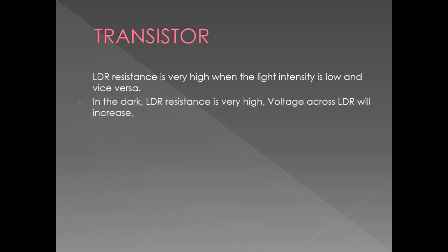Because of that, in the dark, the resistance of the LDR is very high. Therefore, the voltage across the LDR will also increase.